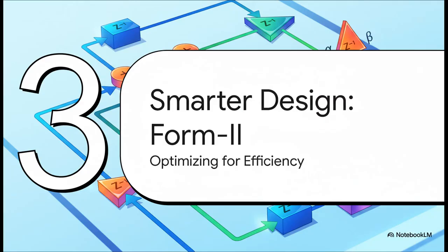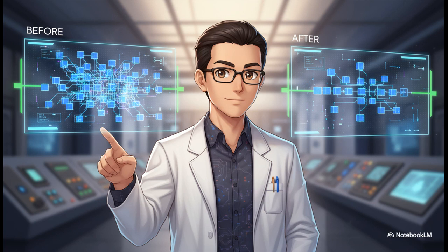So we've got a design that works. That's great. But in engineering, the very next question is always, can we do it better? Can we make it more efficient? And that's where our next blueprint, the Direct Form 2, comes into play. The key question here is all about optimization. Can we build the exact same filter, get the exact same result, but use fewer parts? In the world of digital filters, one of the most important parts is memory, which is represented by those little delay blocks.